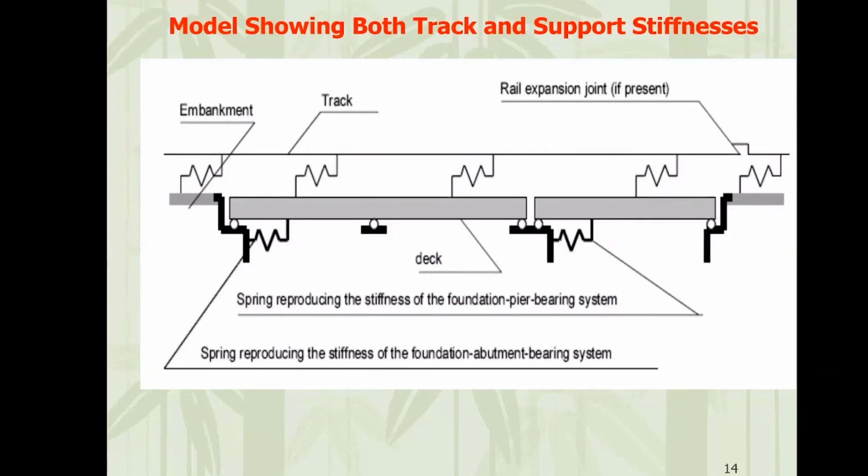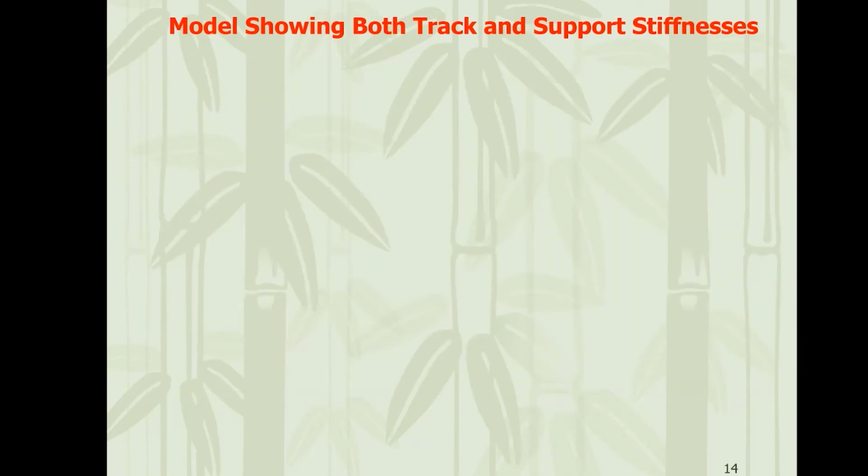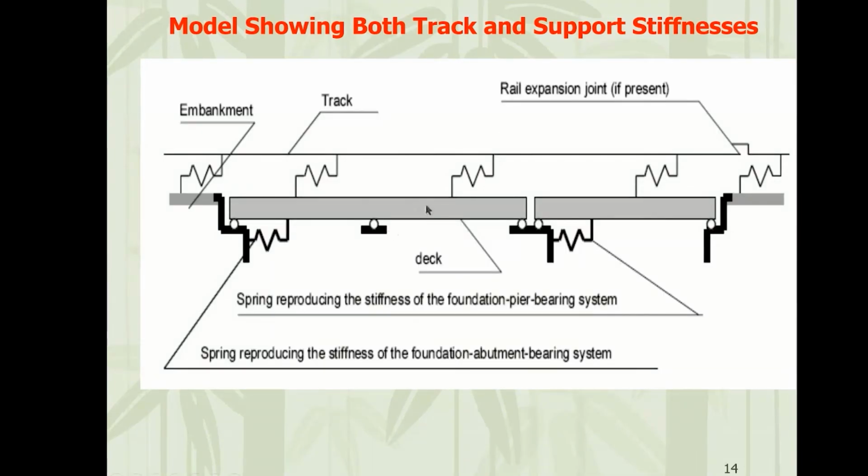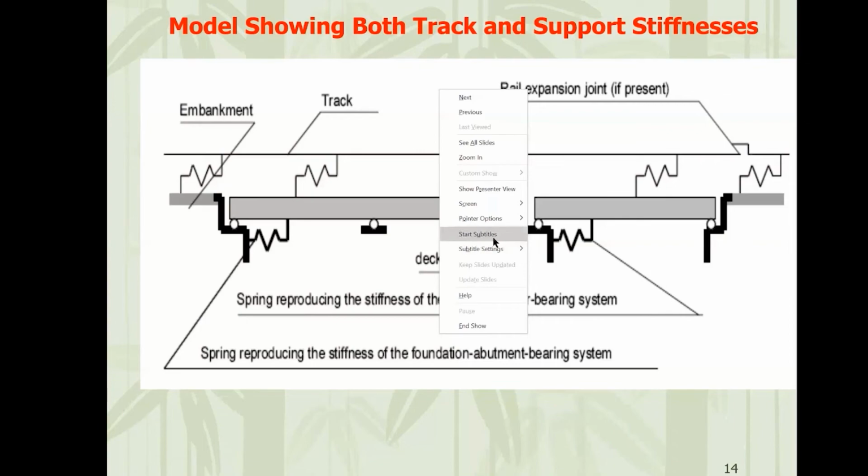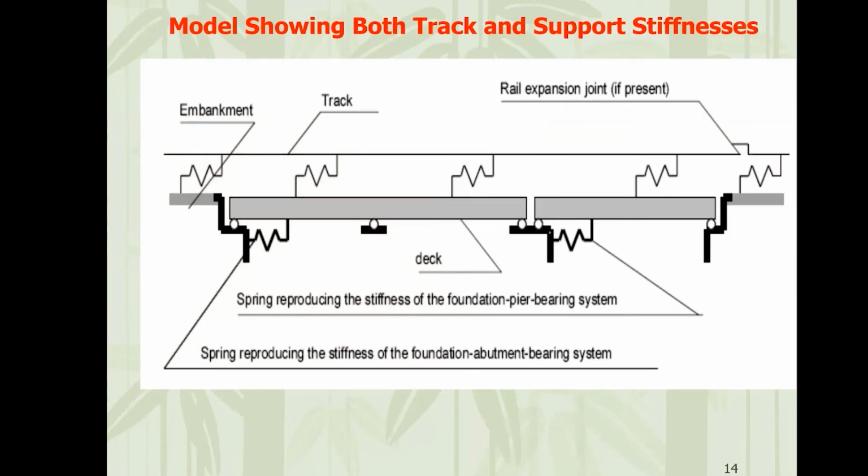Right? So basically, here we do not yet have the practice of building continuous spans, but if you go to railways around the world, people want longer and longer spans, especially for high speed operations, because to control their dynamic effect they need longer spans. But if you go for longer spans, this effect is going to kick in, right? This effect is going to create problems in the track. So because of that we have to control it. Basically, all the parameters that get controlled are controlled because of the track, since the track can become unsafe. So in RSI, the main issue is that we have to take care of the track safety, right? And the forces generated in the bridge, we design for those.